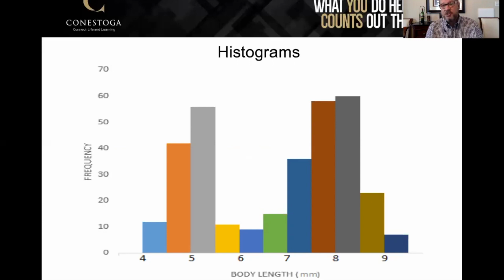One potential explanation could be if the process that cuts this part, the cutting machine, is loose or there's something loose in it, there may be a tendency for it, in that looseness, to bang up against one end or the other, which is causing you to cut parts that are either too short or too long. And that variance may be a result of something that's loose. That's just a theory, right? But you would look at patterns and go, is this a pattern that I expect to see? If I don't expect to see it, what does that pattern tell me about what's going on? And then based on that, what kind of things would I do to start to look at potential causes, right?